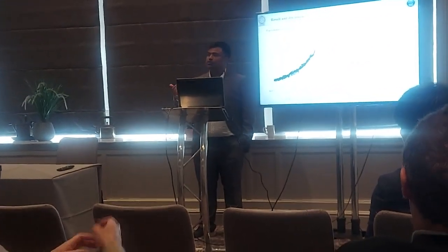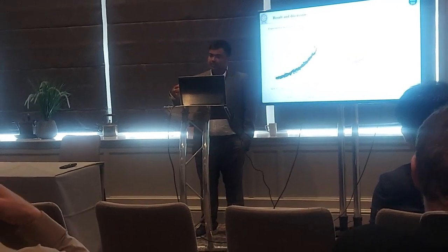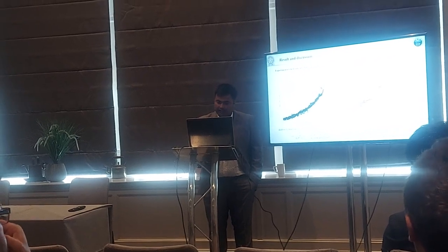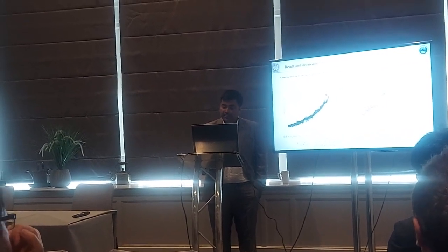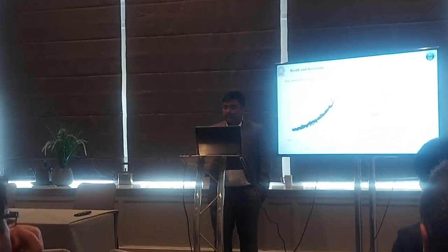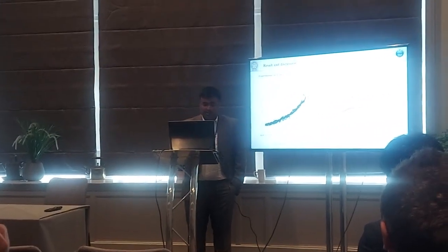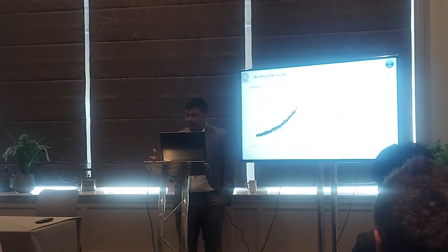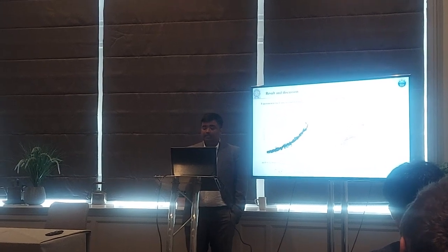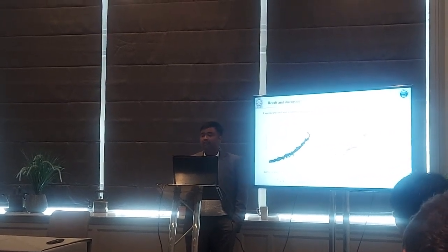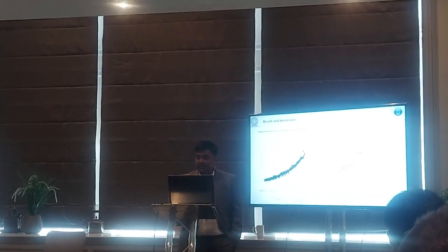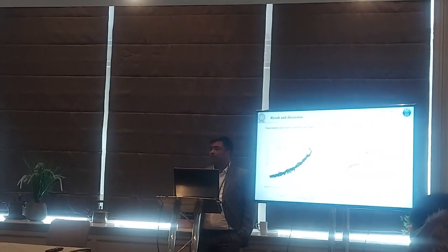Due to the stress relaxation, it compresses the void formation, and then we see that continuously, by increasing the load, the C star value increases because it depends on the LLD, the total load line displacement rate. By increasing the load, the load line displacement increases, and due to this the C star value increases with the load value. After that, the JP I consider, which means plasticity.